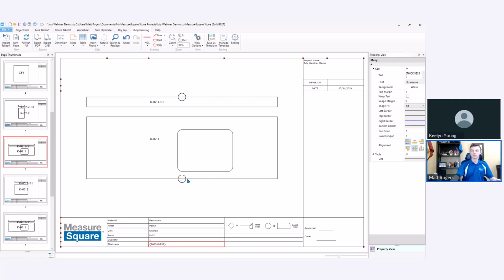Right now in this shop drawing, I'm showing these edge details as a symbol. We can see that I have this little ease edge symbol image down in the bottom right. That just indicates that we have the ease edge here. If I come in, we can turn that to the linear product as a line, similar to the takeoff that we have. But for something like a shop drawing or a cut sheet, we can show this as the symbol to give a little bit more familiarity to the guys in the shop, the guys that are actually using these to fabricate.